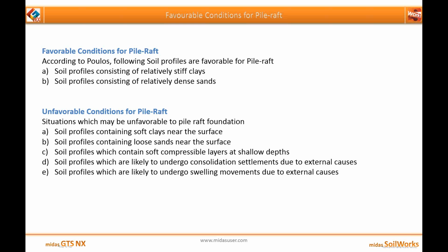The unfavorable conditions for the pile-raft foundation are, first two, soil profiles containing soft clays near the surface or loose sands near the surface, where pile-raft foundations are not recommended. Similarly, wherever there is a chance of consolidation, like where there are soft compressible layers at shallow depths, or where there is consolidation settlement due to external causes, the raft no longer remains in contact with the soil, and all the force is then taken by the piles, leading to excessive settlement in the long-term cases.